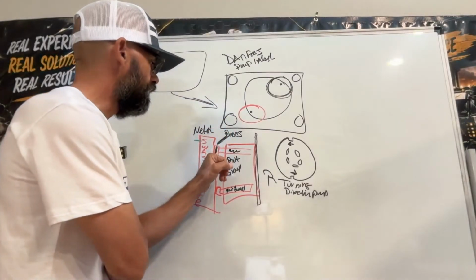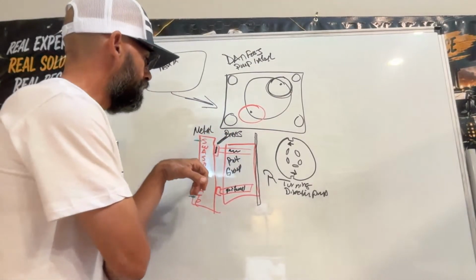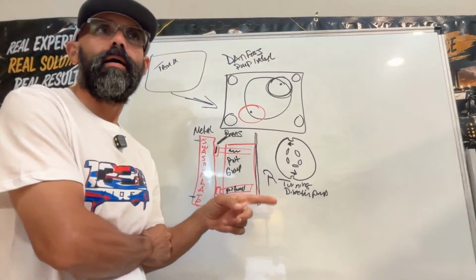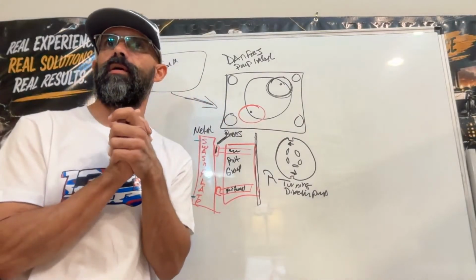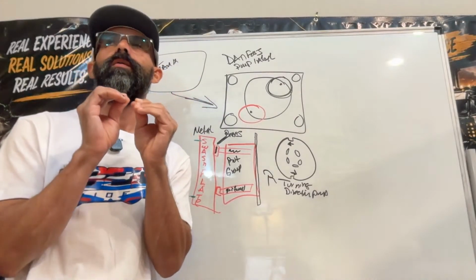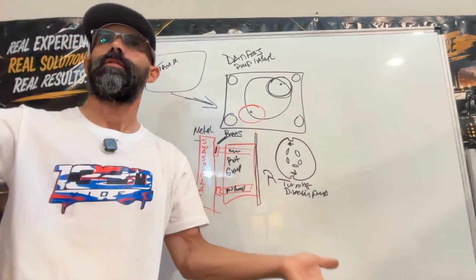Lap the head of the slipper, the brass. Lap the swash plate, the bob plate. When I say lapping, it's a process, right? You have to use a perfectly flat surface, a machine surface.